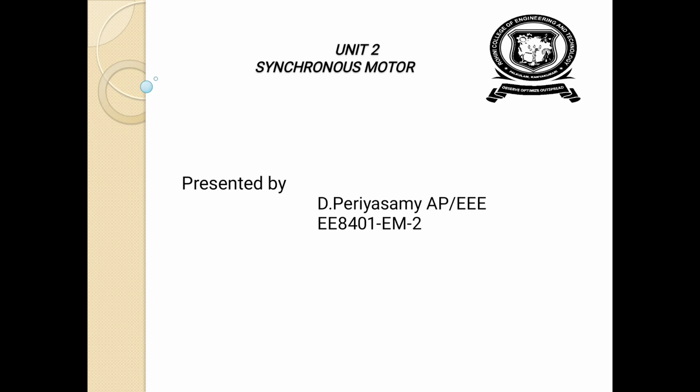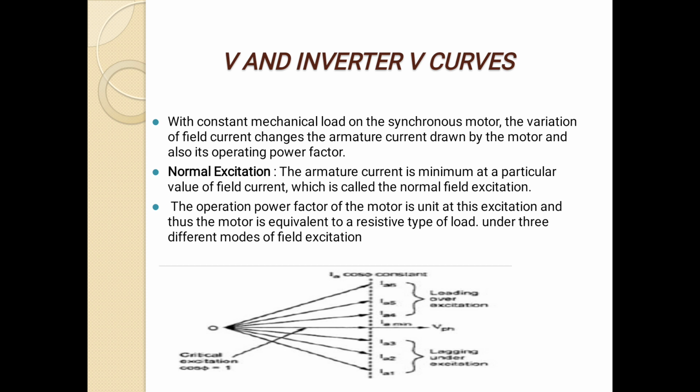Today we are going to discuss unit number 2, synchronous motor. The topic is V and inverted V curves. When the excitation of a three-phase synchronous motor, taking constant power P from a constant voltage supply, is varied, the power factor will change.